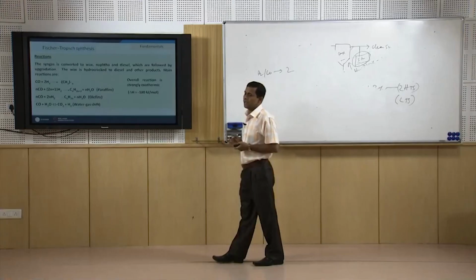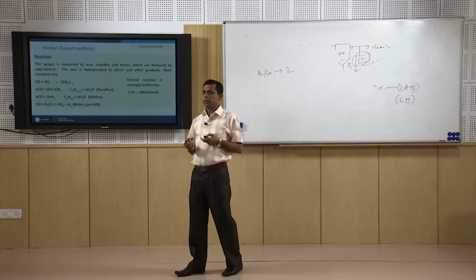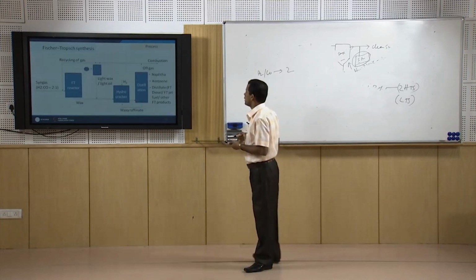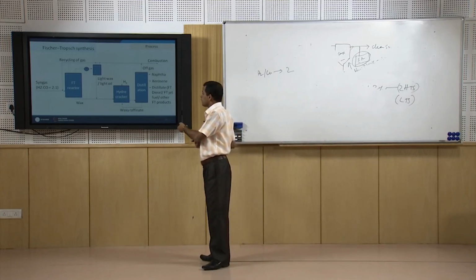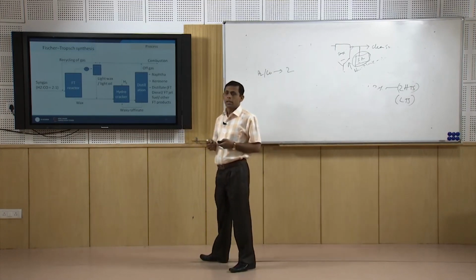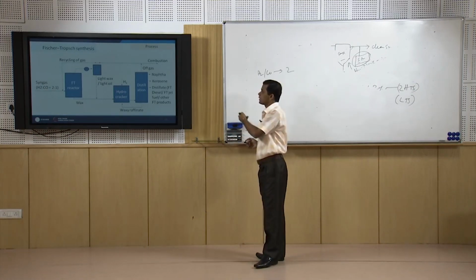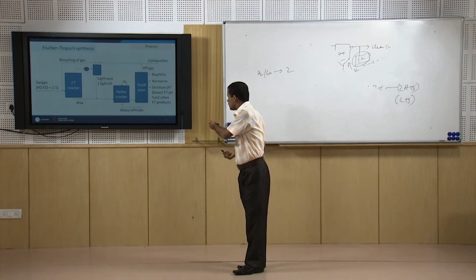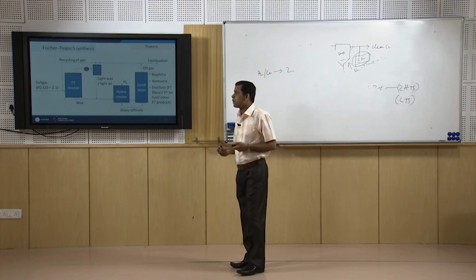This syngas is reacted in an FT reactor where it is converted to wax, and that wax is further processed through a hydrocracker. After distillation we get different fractions: naphtha, kerosene, distillates, and the lower part, the waxy raffinate, is recycled to the hydrocracker.